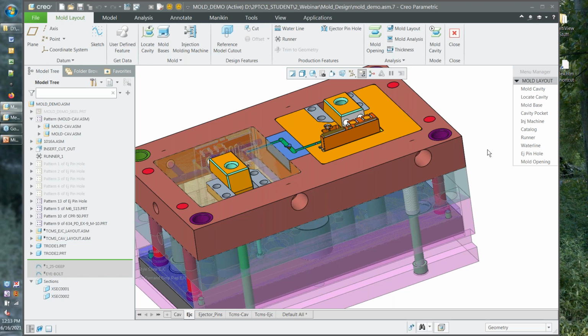When we do family tools and we have multiple cavities, but the cavities aren't all the same, a lot of times that can be a huge asset to be able to make that molding representation from the Creo mold layout level to share with a simulation product upstream to determine that you're getting the expected results in a family molding, as those can be some of the toughest stuff because of the dissimilarities between the components themselves, and therefore the response to the melt flow and the molding operation physically as it happens.